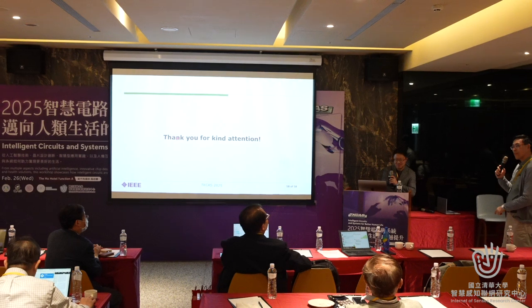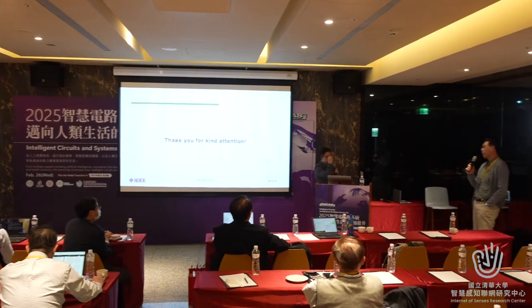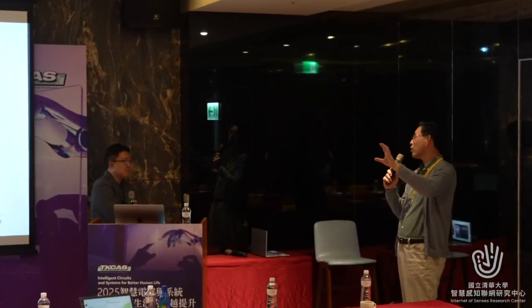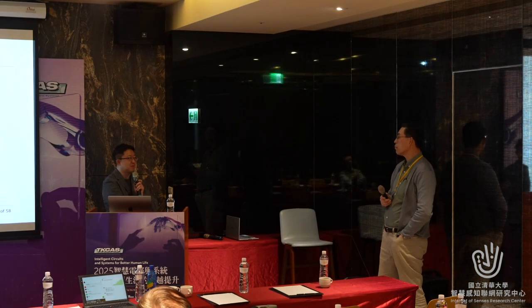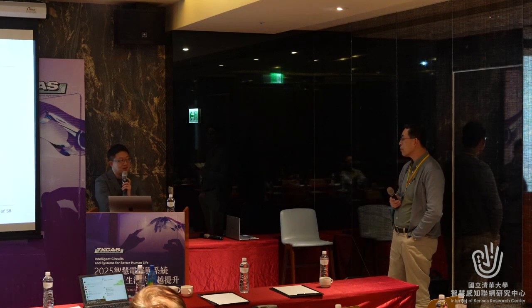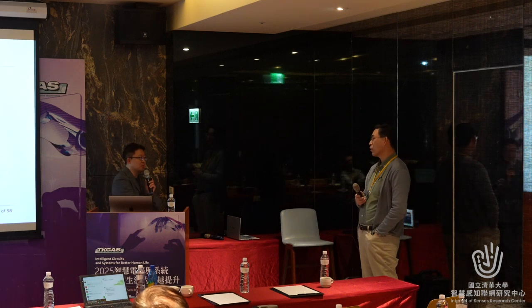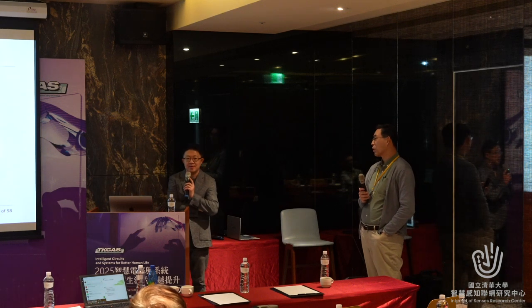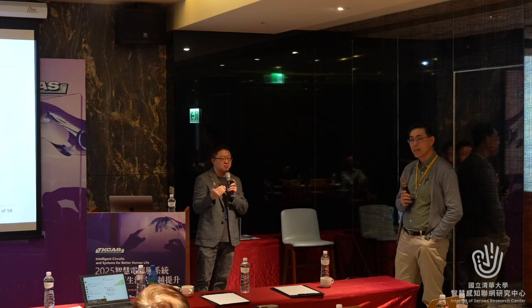Yeah, let me ask you one of them. You mentioned high voltage stimulation. Yes. Right. So, what's your opinion? Should we use high voltage devices, or just stack many low voltage devices? So if you don't have an area restriction, going with the high voltage device is a safer solution. But if you really have to implement a scalable solution, then you have an area restriction in this case, right? Then there is no other way than using a normal voltage device, because of the layout of the high voltage. Right. But you have to put in some more safety functions, overcurrent protection, whatever.